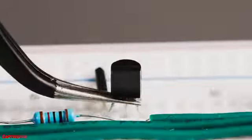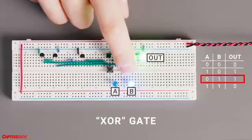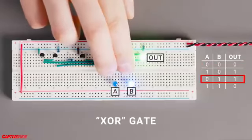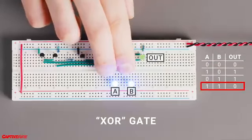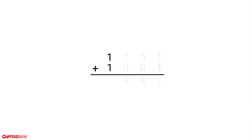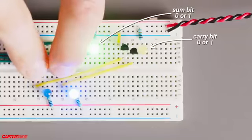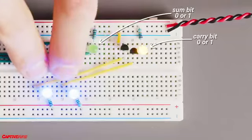Of course, I've gone ahead and assembled the circuit, and you can see that when either input is on, the output is also on. But when both inputs are on, the output turns off. So we are in essence adding 2 bits together. The problem with this setup though is that it doesn't account for our remainder. Like when I add 1 plus 1 together, the output is 0, but we should have a way of knowing that there's an extra bit that should carry over to the next bit column. And with that in mind, we can add some more circuits like an AND gate to indicate that the sum has resulted in a carry bit, shown here as this yellow LED light.